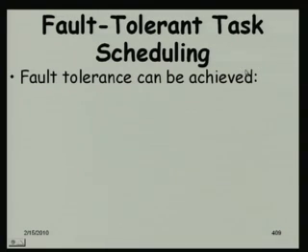One is to have separate dedicated hardware, separate nodes, where you run extra copies of the task called backup tasks, and when one node fails, that takes over. Or there can be a voting where they decide which node has failed. We can't really decide which node has failed because it might be producing incorrect results, so a voting solution can be adopted.